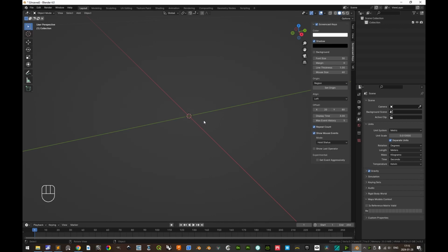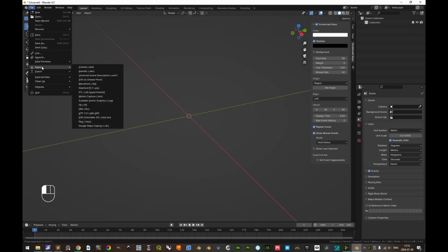And then if you want to import more Rhino models using this very same workflow, make sure to import them individually, each into one separate empty scene. And then you can append or link via the file menu the other imported model into your main scene. Now let's make sure to import our exported OBJ.